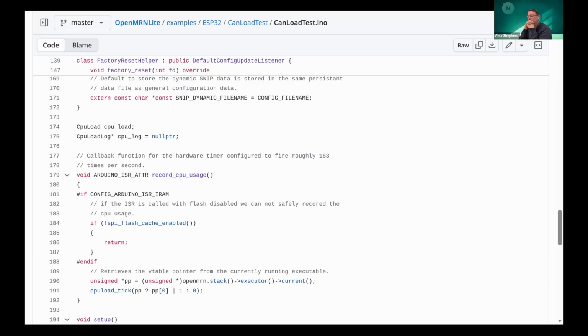But you also have to be aware that different ESP32s have different cores. The original is double core. The S3 is also double core, but different megahertz. And then the C3 is single core, but it's not a Tensilica core. It's a RISC-V core, but it has a different megahertz as well. Again, that is something that you can actually go ahead and just try.